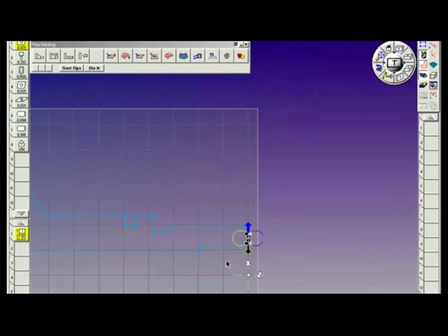In this case, we're going to start machining on the face. The two circles that appear represent the tool or the insert itself, cutting on the right or cutting on the left of the selected feature. The arrows determine the cut direction. The white square marker is the start feature selector. The black square marker is the end feature selector, and we'll get some more understanding of this as we progress through the part. The white circle is the start machining marker.